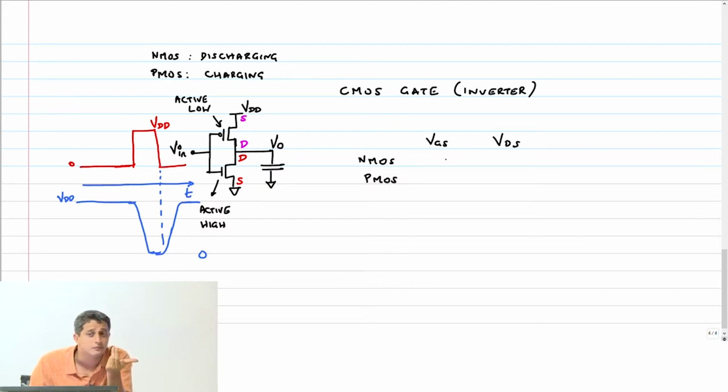It is V in. VDS is V out. What about the PMOS? VGS is V in minus VDD. VDS, be careful, is V out minus VDD.